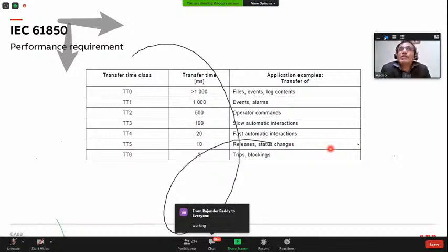So I assume that we do a ratio between the second harmonic and the primary current, then we will see if it is crossing some limit. If it is crossing some limit, I think it blocks the protection.